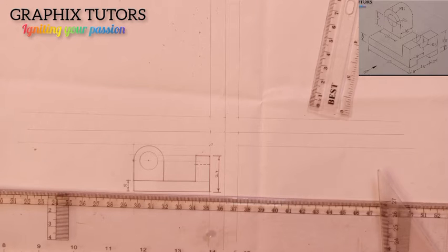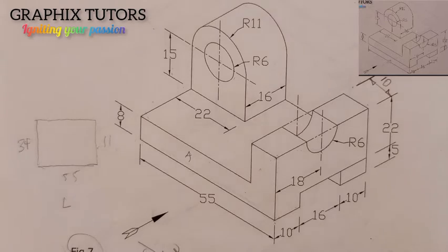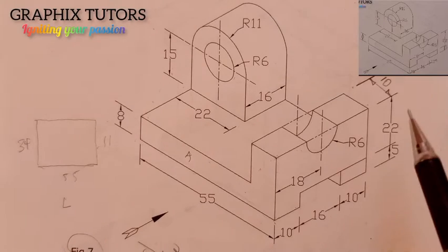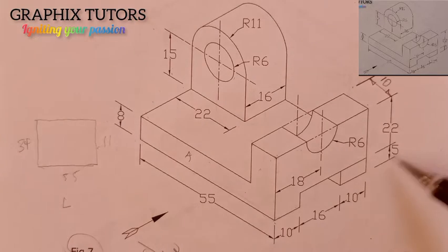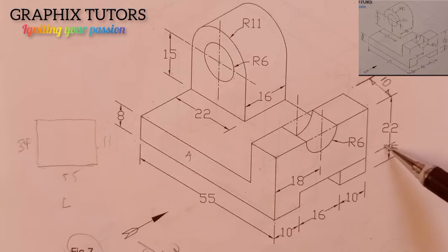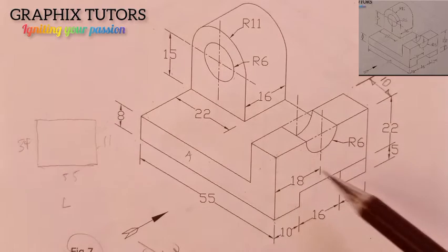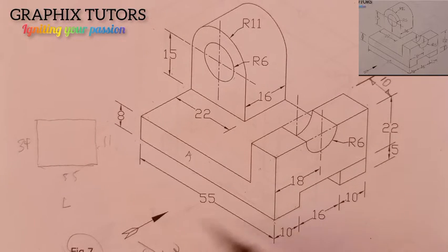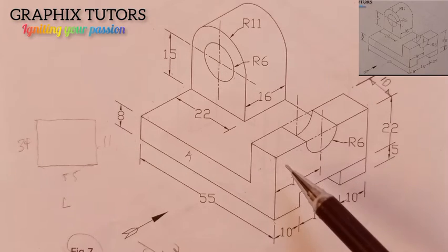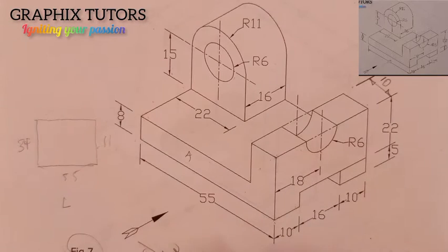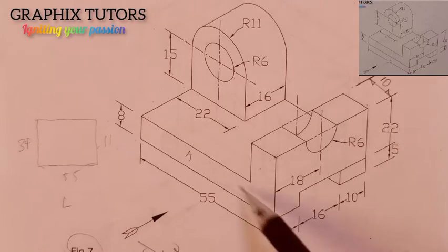Right? Now similarly, there's still another one again. Let's look closely. At this point here, right? There's a line up here which is 5, which is this thickness here, and it's going through in. So that means I cannot see it from looking at it from this point here. So to show that there's a cut through in between this figure, I'll use the line with a height of 5, and I'll demarcate this figure from here to here like this.